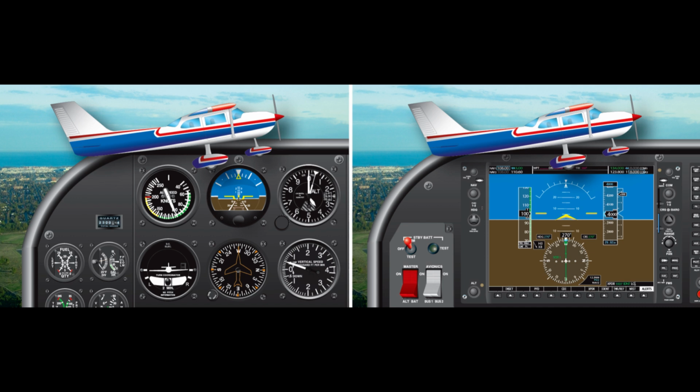After the airplane is established in level flight at a constant altitude, climb power should be retained temporarily so that the airplane accelerates to the cruise airspeed. When the airspeed reaches the desired cruise airspeed, the throttle setting and the propeller control, if equipped, should be set to the cruise power setting and the airplane retrimmed. Climbing turns.